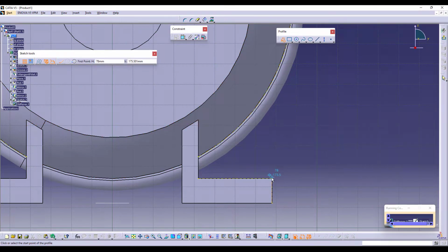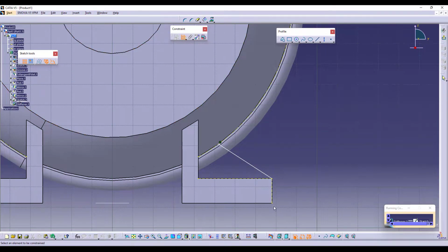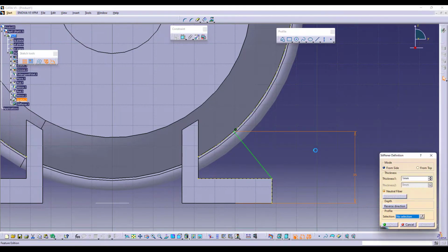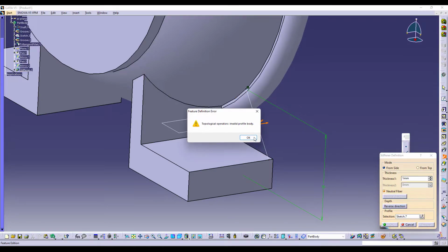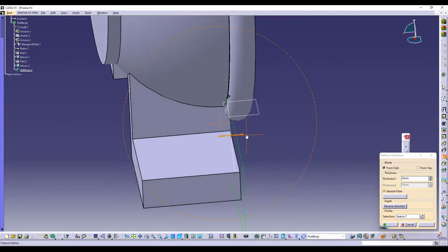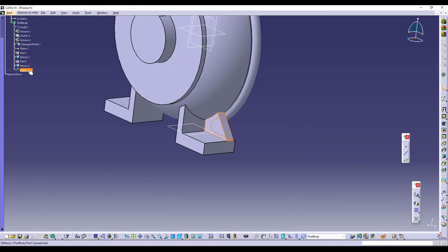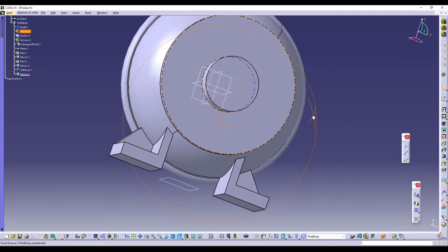Now the rib profile is this way. The height of the rib is 35, again the thickness is 8, so I'd like to give that first. Now 35 mm is given from here, and once I say exit, it asks for the thickness. It is only on one side, it is not on both the sides, so I'd like to give it on the other side, and the thickness is mentioned 8. Okay, as 8. Now let me again mirror this as well, because this is also onto the other side. Again I am taking a mirror and then doing it on the other side.